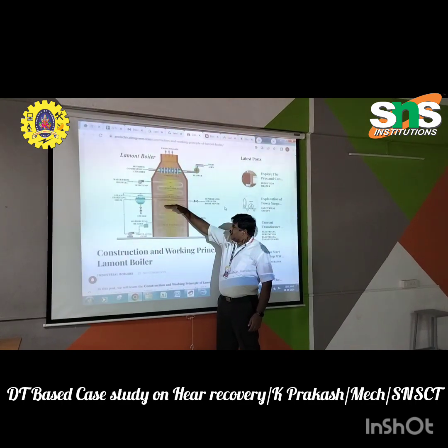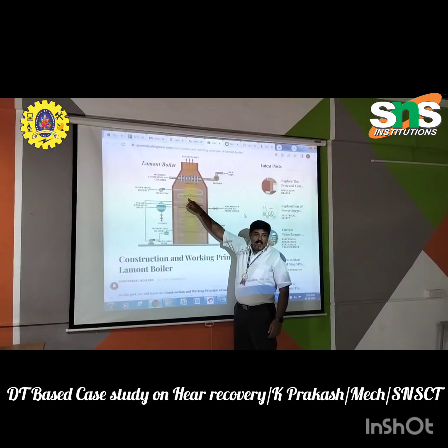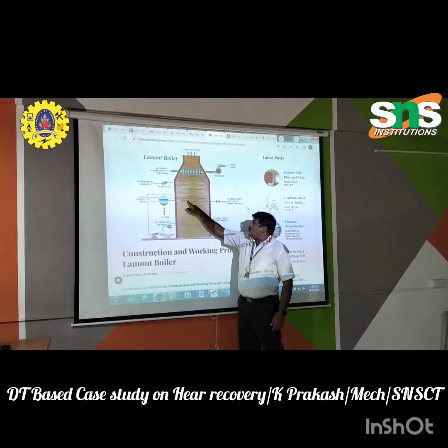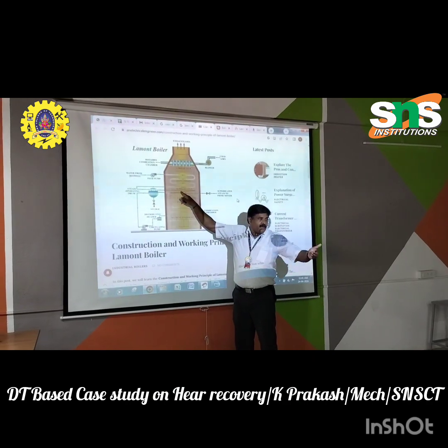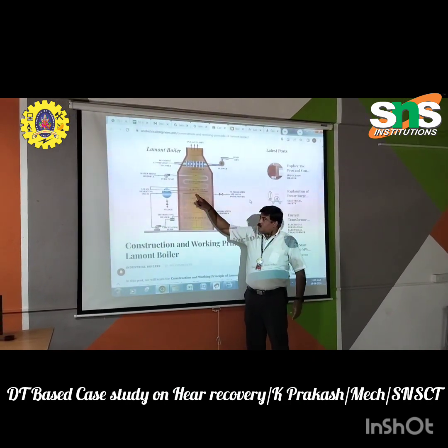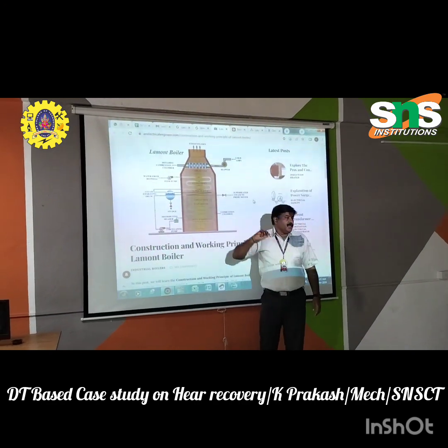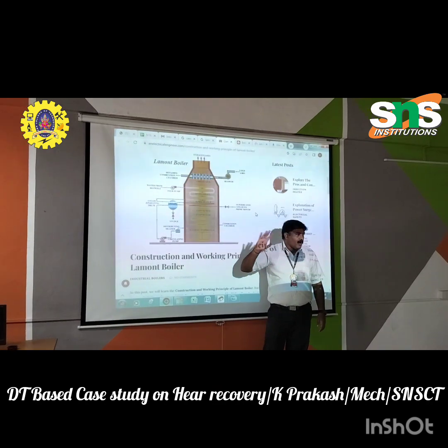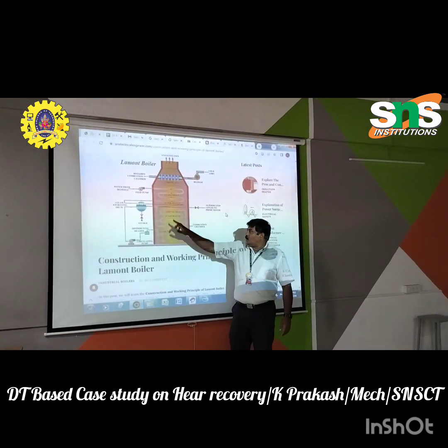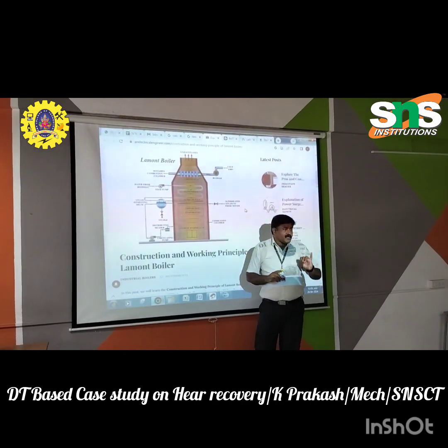After completion, the waste heat in the flue gases is initially used in the superheater. You told that 25% of the heat is wasted. So first, this superheater absorbs the heat. It traps some amount of the heat which is going outside as waste, so that the temperature of the superheated steam can increase. This is the first method.